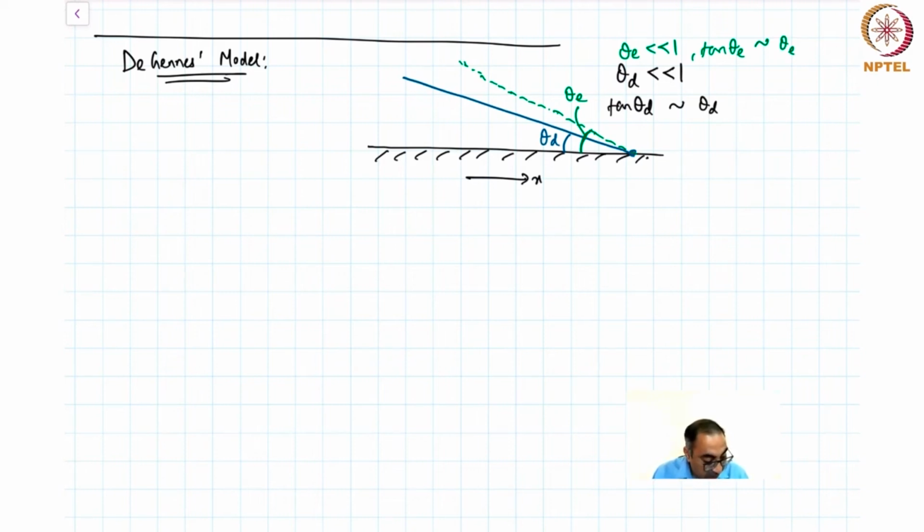So what is the model primarily about? It says that there is an unbalanced contact line force at the contact line, and if the contact line is moving, then this product of the force times velocity, which is the work done, or the rate at which work is being expended, has to be exactly equal to the viscous dissipation that is being caused inside the fluid. So the viscous dissipation is basically causing us to expend a certain amount of energy to move the contact line.